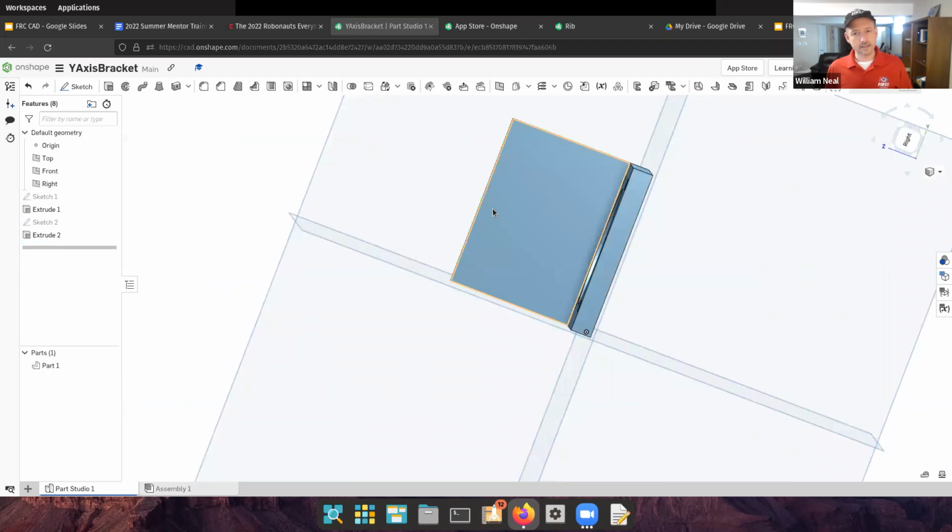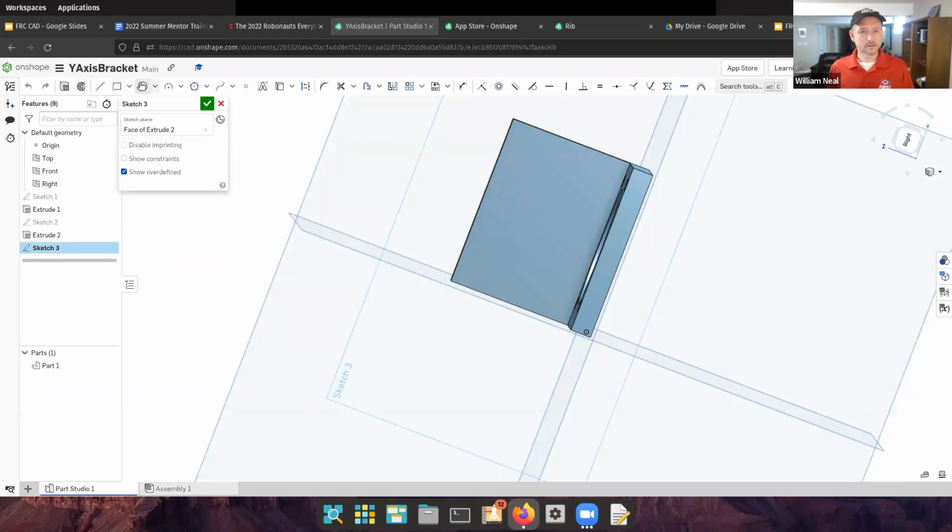And so I'm going to make a sketch right here. And there will probably be some holes maybe towards the top there. First, I'll make a sketch and 2 5mm holes. There's one here. Oh, I made 2 of them. I'll just drag another one around. Whoa, escape out of there. Try that again. There we are. And let's make them exactly 5mm with some constraints.